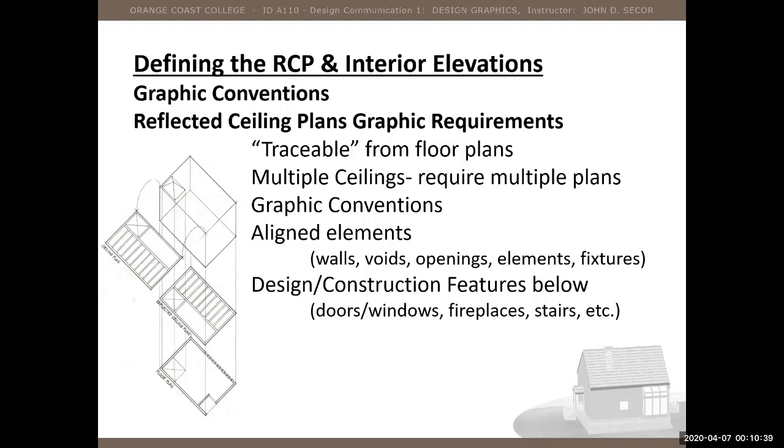That means you can lay down your floor plan, you can outline it and trace it. I wouldn't draw it super heavy. I would draw it light so that you can remove the sheet underneath it, and then complete the drawing with more line weight applications. But the idea on it goes pretty quick. So that's an important piece.